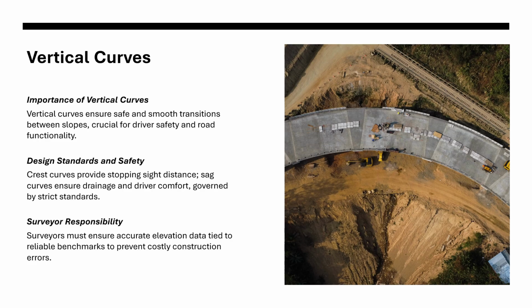Again, in Texas, it's typically NAVD 88. And if those benchmarks that we're using are off, the entire vertical picture will be distorted. Similarly, when a design profile is created, it must be checked against datum and tied to the same control framework. If it's not, the grade stakes set in the field will likely be wrong, leading to costly construction errors.